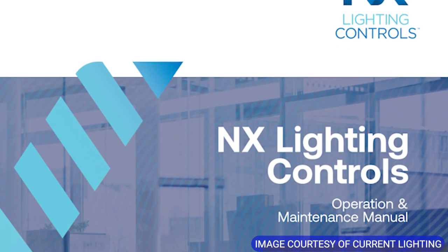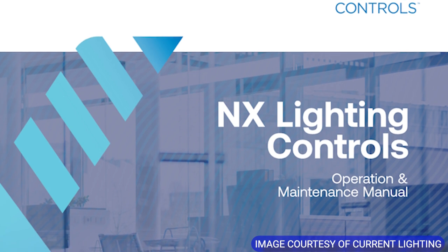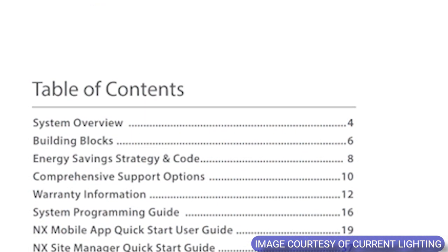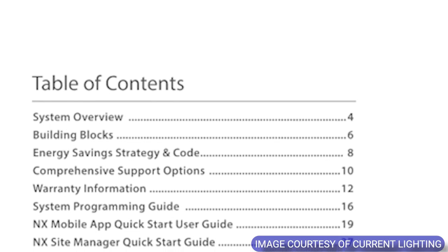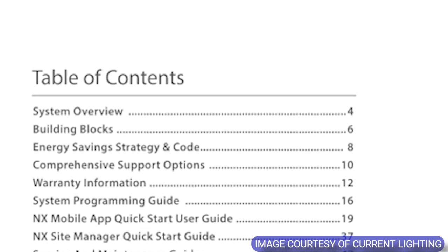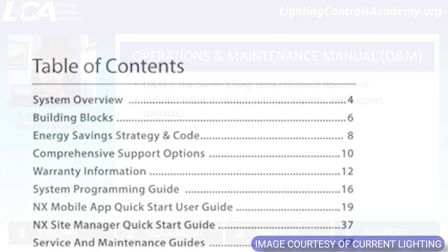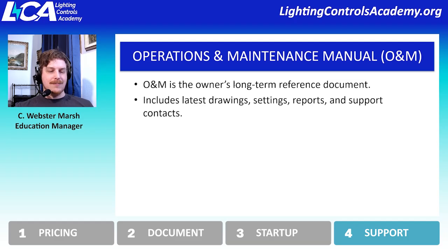But at the end of the day, this document is just the long-term reference document. It should have everything that is up to date. So the drawings, the settings, the reports, any contacts that they need to reach out to for support, the submittals, the approved submittals, what's referred to as the as-builts, which is the revised drawings to reflect what actually got installed rather than what was anticipated to be installed.